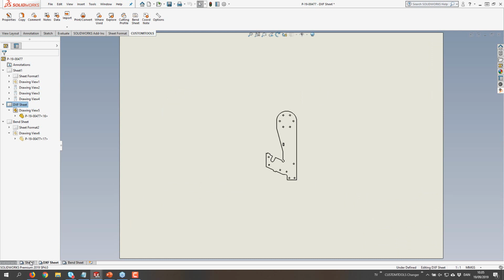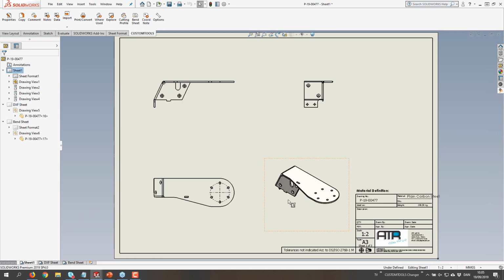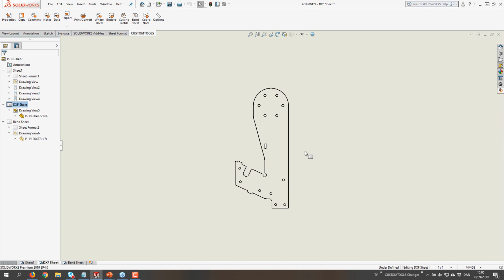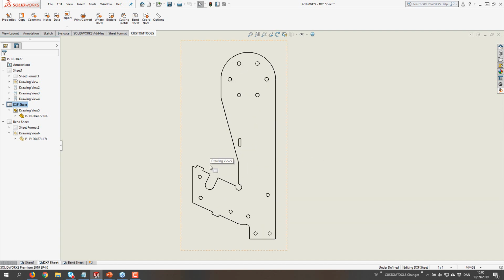And before I go into that, basically I want to show you, we have some countersink holes coming in from this side and from the back side. So on two sides of this part, we have countersinks, and we also have some threaded holes. So a 3/4 circle is included in this one. But if you look at this one, we actually cleaned it up perfectly, so it's ready for laser cutting. We removed that circle that is around this hole, and we removed these 3/4 circles that indicate there is a thread.